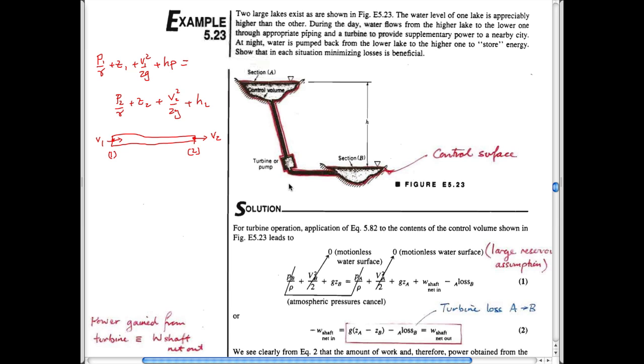And so this is just an illustration of the bag across the table issue. For me to drag the bag towards me, I have to expend energy. For me to get it back to its initial position, I also have to expend energy. So I've expended probably double the amount of energy to take it one direction. And pumped storage schemes are the same way, in that there is no free lunch, and there's some energy loss in the system that you never get back. And so this question is basically looking at that. It's saying you have an upstream reservoir which flows down to the downstream reservoir. And if you have some head losses in the system as you go through here and generate electricity, then how are those manifest?